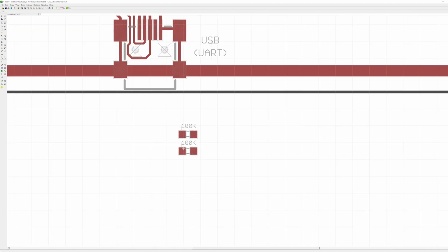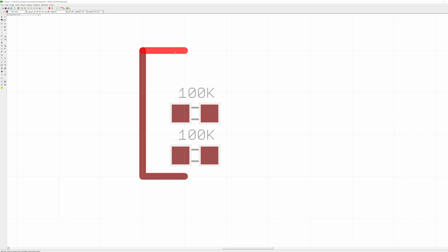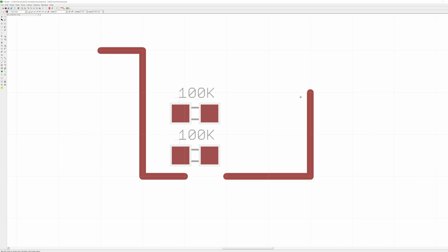I build these things one time. Like I built the definition of this particular resistor, which I believe is a 0603 resistor, which has a very particular pad size and pad spacing. I built it once and I just copy it and move it around. And then I might select the wire tool and then either the top or bottom trace. Now it's going to be locked to the grid, so it's not going to actually select the resistor. But the idea would be I would take one half of the resistor, connect it to something, take the other half of the resistor, connect it to something else, and then that's it. That's how I use the tool.